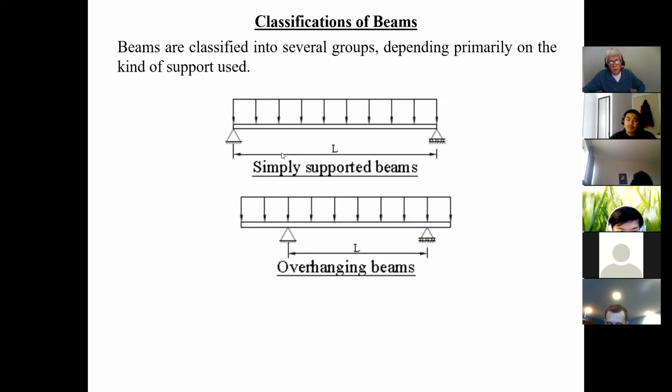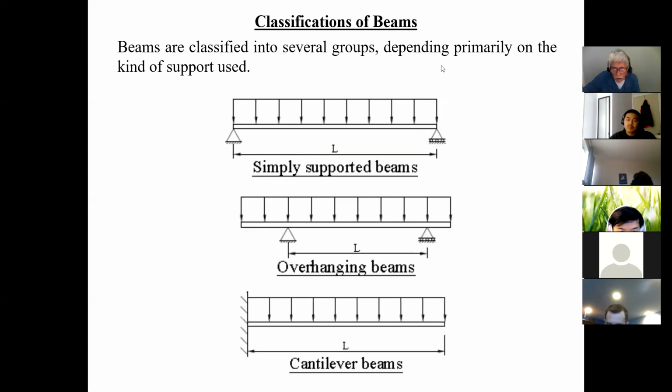And of course, here we have what we call a cantilever beam. In other words, it is being held at one end and there's nothing else supporting it. Now here, this cantilever, if you notice, I represent it with this. In other words, it has to be fixed here. What that means is that I'm preventing it from moving up and down, and I'm preventing it from moving side to side. And also, when this thing wants to rotate, everybody can see that this beam wants to rotate from its original position. There's got to be something here to prevent the rotation, the reaction of that rotation.